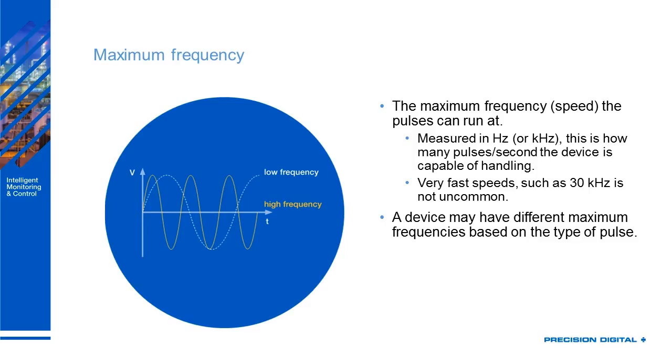So you need to be aware of what the maximum frequency is for your devices so you can make sure that the generator's maximum frequency is equal to or lower than your receiver's maximum frequency. Otherwise, you're going to have all kinds of strange behavior, from maxing out and just showing your maximum value for everything that's over, or you could even start getting some kind of strange aliasing going on where the results will be unpredictable.